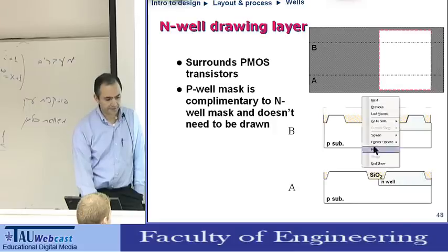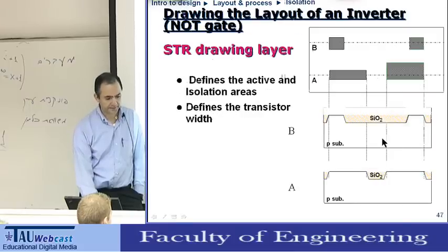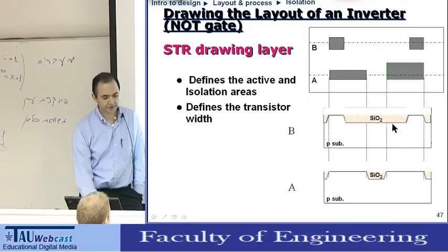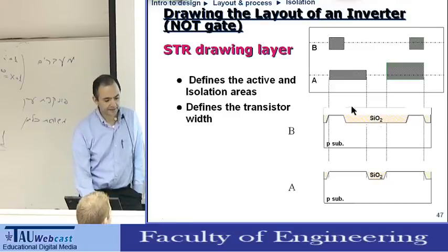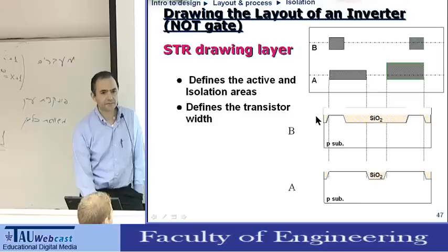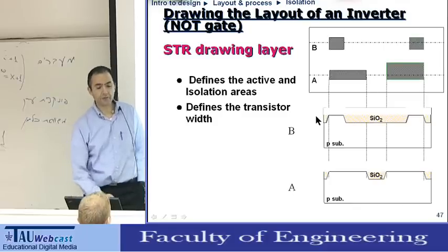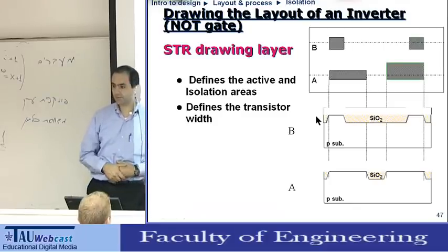Okay. So what I didn't mention, and I didn't do it properly, so I'll do it again. Here, after we etched the trench, we fill this with SiO2. We fill this with an isolation material, and then we made it smooth. How did we make it smooth? With polish. Now, how did we know where to stop?